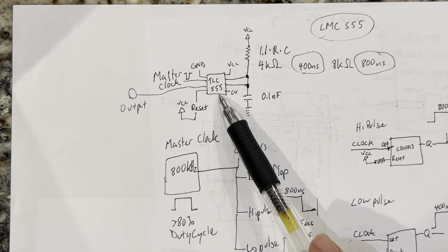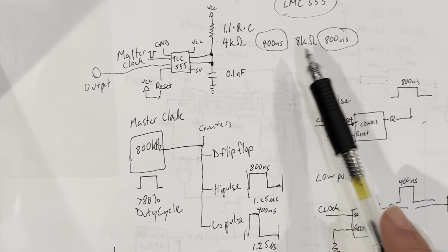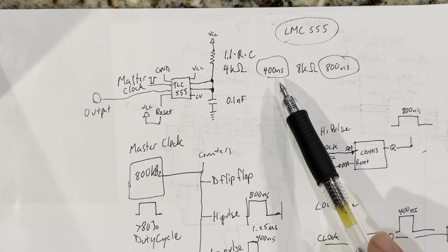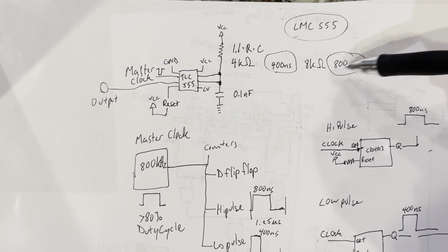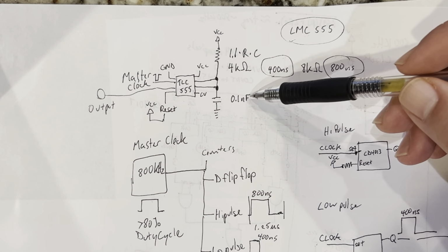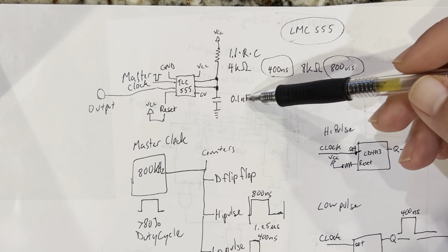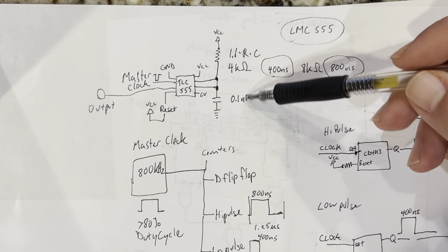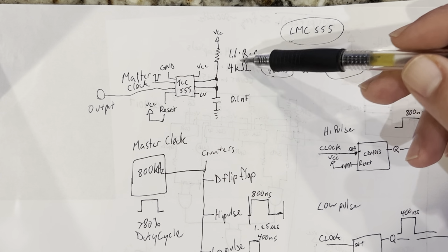that can be triggered by the master clock and be able to deliver a short enough signal of 400 and 800 nanoseconds, and you know, to calculate these are fairly quick. Because the nanofarads end up corresponding to nanoseconds, you just take this number and multiply it out, and it ends up being somewhere like 400.